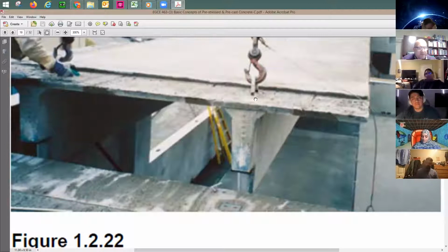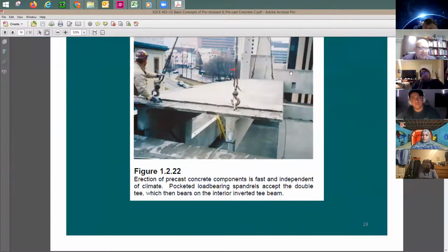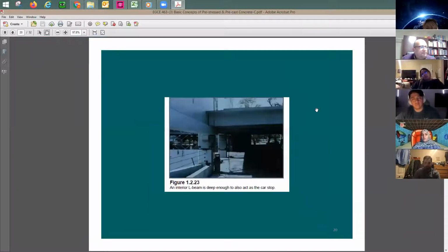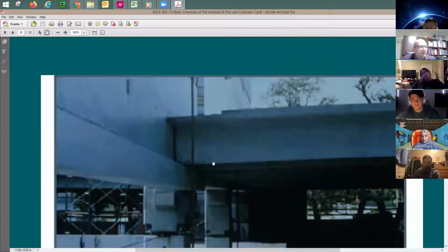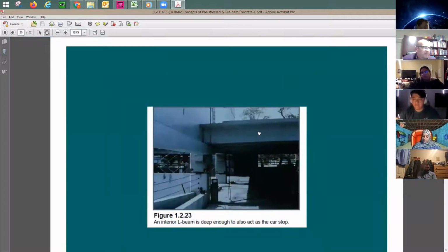You really need to be careful when you are using hangers, like the way Spancrete would do. Look at this, this is going to be the straight one. You can either sit on a ledge or you're going to have a hanger. So in this case, you have a straight end of the double T and you just let it sit on the ledge. One of the methods that they do.